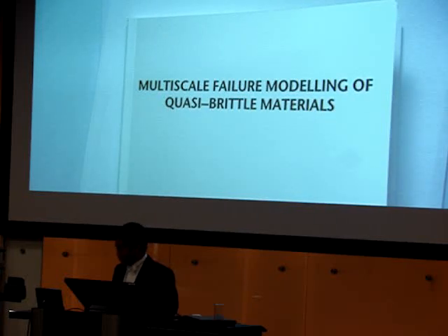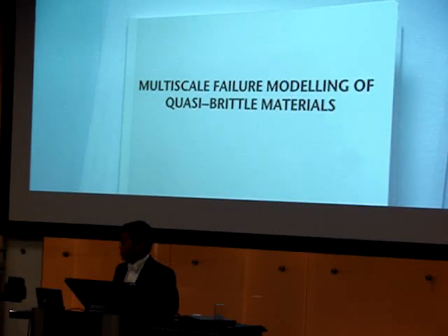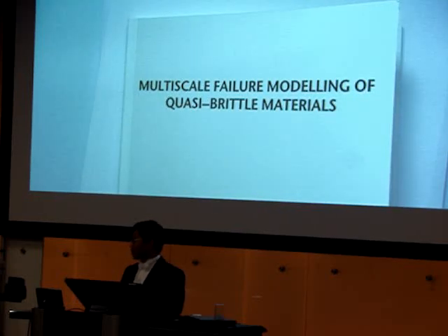Yeah. But then do you have a direction for this C parameter, how to measure it experimentally? Is that really simple? No. C parameters, even now in the literature, measuring the C parameter is, I think, a very difficult task. And usually people have to use inverse analysis that combines experimental observation and numerical analysis to define that C parameter.